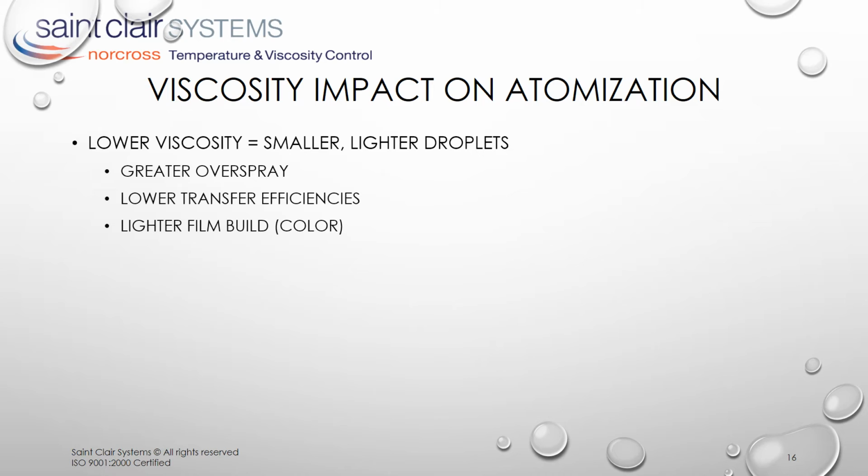These smaller droplets also present more surface area to the air, which promotes solvent evaporation through the droplet's surface. The rate of evaporation, which increases with temperature, can result in dry spray, with a significant portion of the solvent lost before the droplets even reach the target surface. With insufficient solvent in the coating to facilitate flow out, gloss suffers. This can also have a negative impact on adhesion. Fortunately, evaporation is less of an issue with 100% solids coatings.